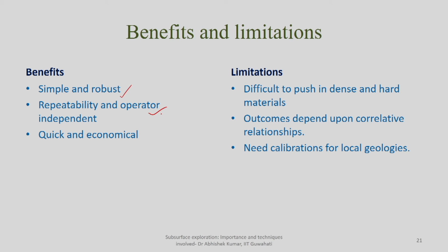It is repeatable and operator independent, quick and economical, but a limitation is that it is difficult to push in dense and hard material. The outcome depends upon correlative relationships. So whatever correlative relationships I showed you are general. Sometimes if you have a site specific or region specific correlation, these may not be applicable. Unless those correlations are known to you, you will not be able to interpret the data, or every time you have to develop a correlation, otherwise you will not be able to find out different parameters.